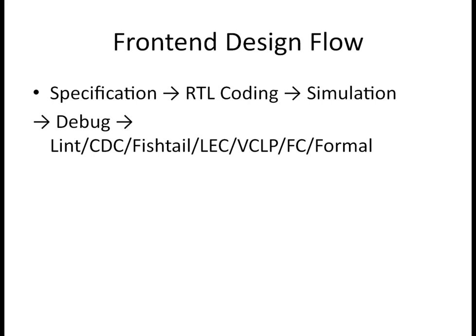In a few cases, when your data is changing very fast, the two flop synchronizer may not be sufficient. In that case, we'll be using a three flop synchronizer, where we add one more flop stage in cascade to synchronize the signal from one domain to another. This is one of the techniques in single bit. Let us discuss a few more techniques for multi-bit.